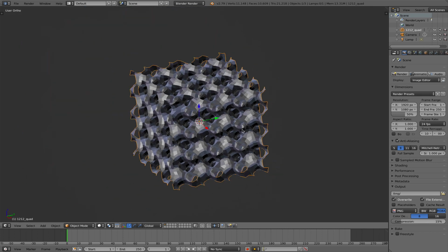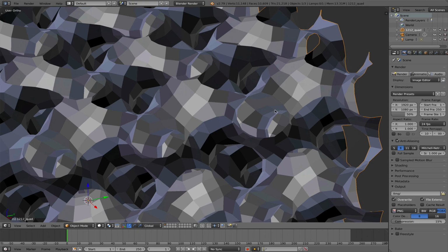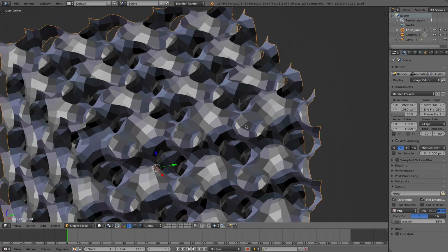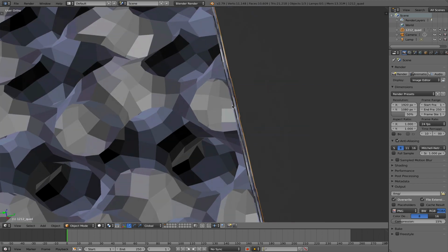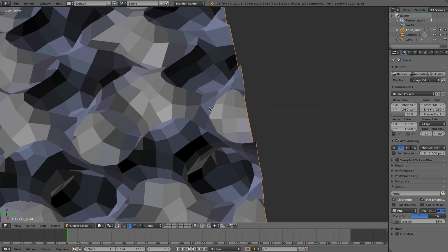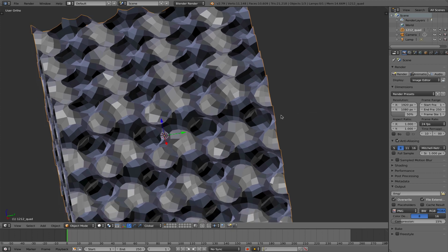And I have deselected everything and then right click to select this cube-like structure. And we can see there are quite a few faces in here. It looks a little bit structureless, but we get to that in a moment. It's a thin surface constructed from quad faces, so to speak. And as you can see here, I'm using the pie menu that's available in Blender.